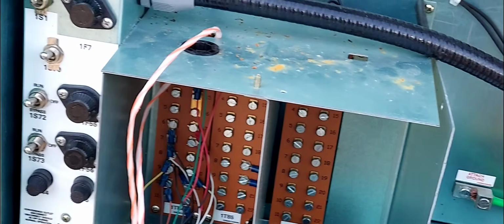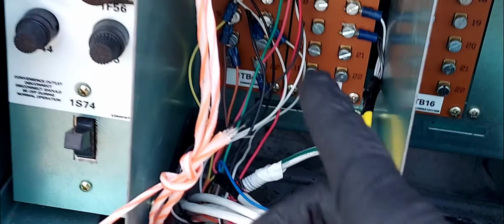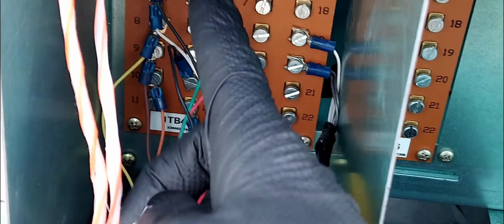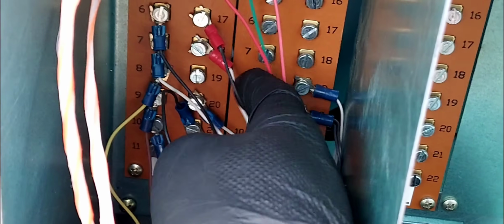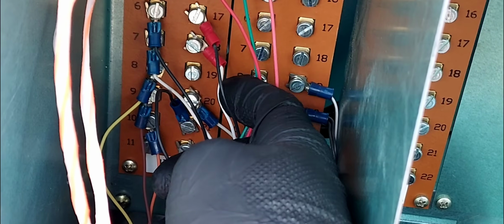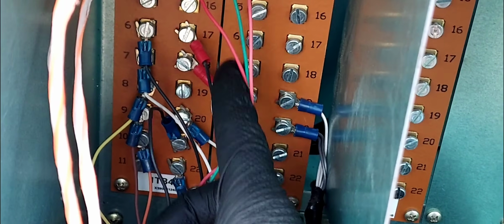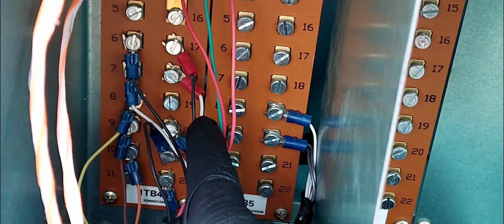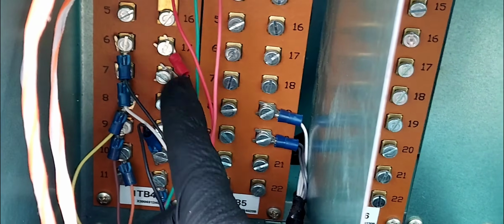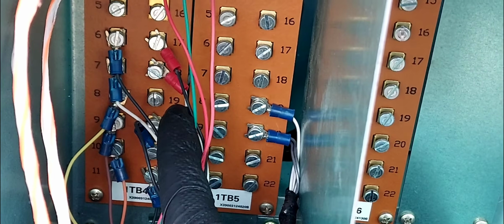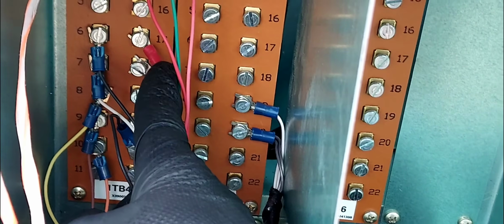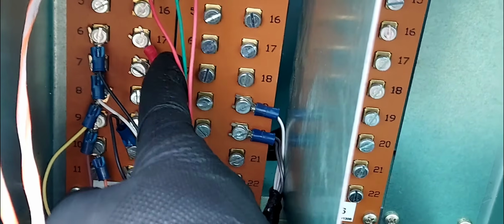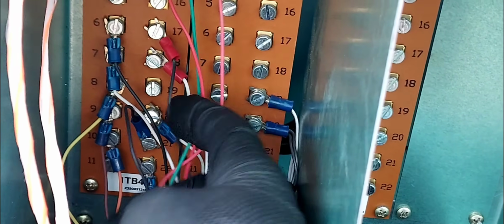but I'm going to go ahead and just remove those two wires that are connected to it and check that these wires are in fact not open, they're closed. Now if that's the case where these two wires are closed, I'm getting continuity, so I know that I have to move to the next phase of the troubleshooting, because that's not the issue. The external stop points right here are good. So let's go ahead and remove one of these wires and check them for continuity to see if they're closed. Stay tuned.